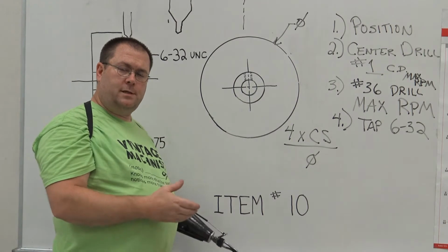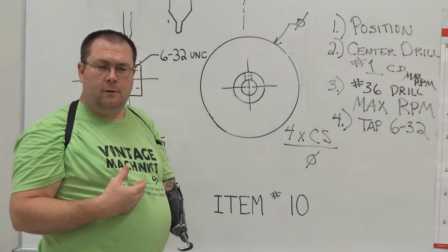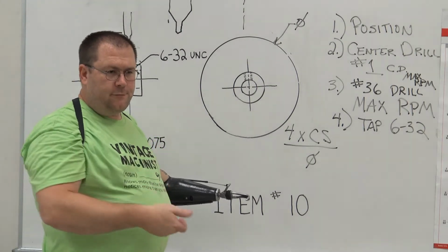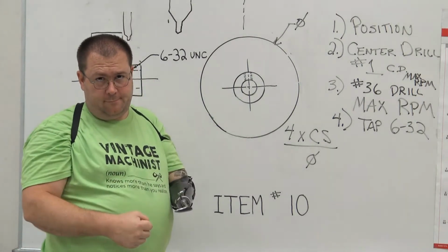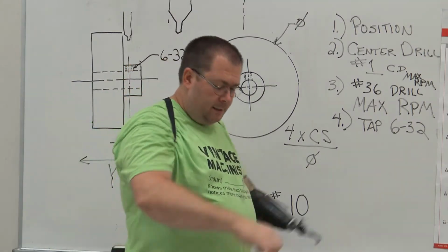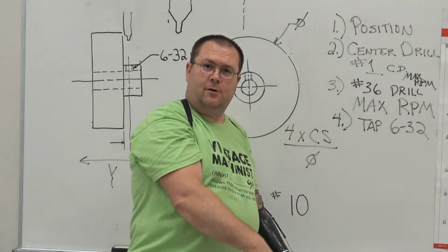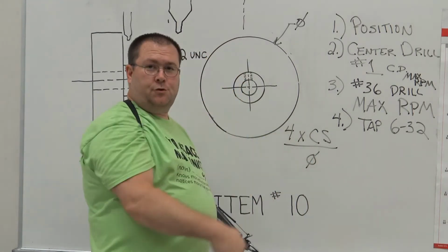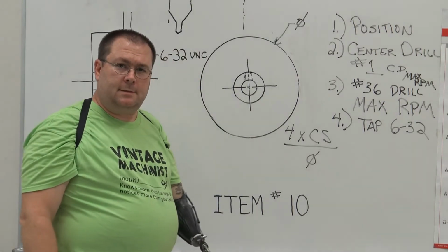Well, if it doesn't force it to cut good and straight, then we have to make sure that we fixture it in such a way that it's forced to cut good and straight. Because if you start crooked, if I were to take a stud and put it in a vise and take the die and start doing this, the likelihood that it's straight to the center line is very slim. Well, if it starts crooked, it's going to finish crooked. You're going to have bad threads.